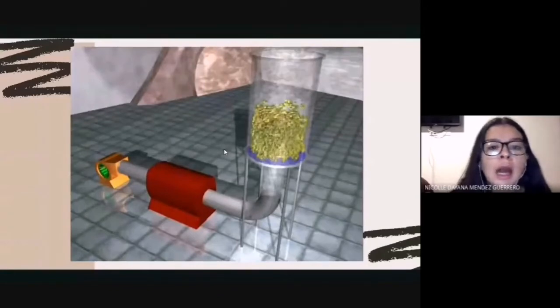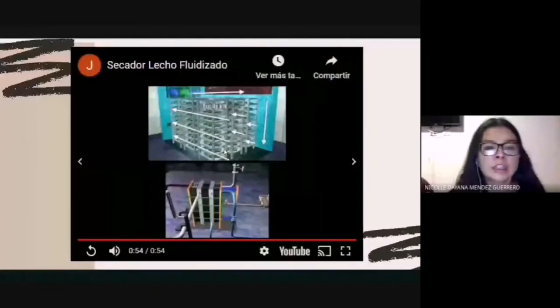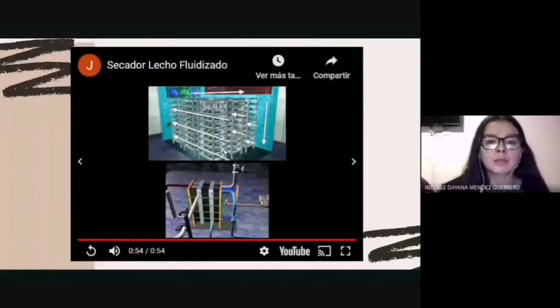As the product dries, it becomes lighter and is carried by the fluidizing air, and is discharged to the dust collection or bag filter box. This process guarantees a fine powder-like final product with particle size close to its primary size and extremely low moisture content.